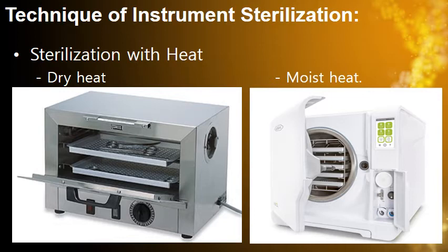The use of steam under pressure, what will it cause? It will cause the elevation of the boiling point of the water. With this elevation, the steam that is generated has much higher heat, which means less killing time. This is the core, or the basis, for the work of the autoclave.